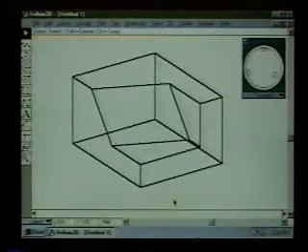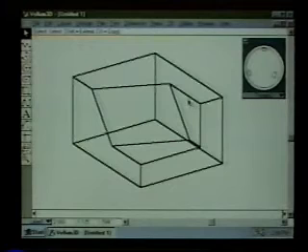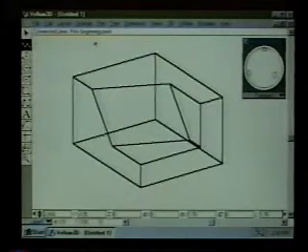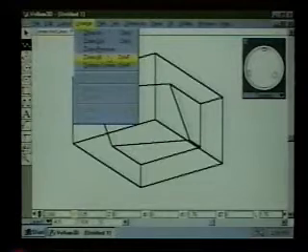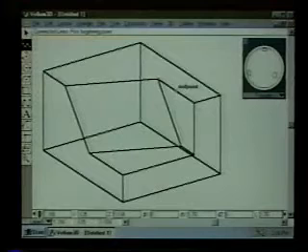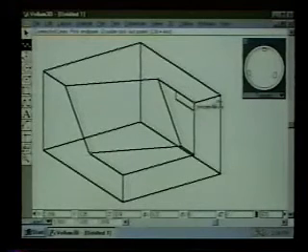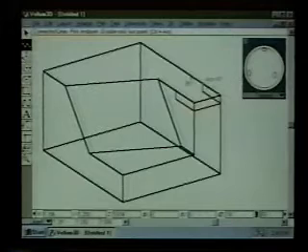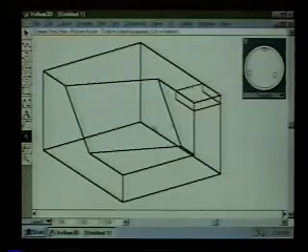Now I'm going to do some other operations. Let me put a notch in this end corner here. So I'll use the connected line tool. Let me say zoom all just to get this as large as I can. And then this notch, I just go and I find a midpoint, I drop down a little bit. And these alignments, again, happen automatically because of the drafting assistant. And then using those red lines to act as trim boundaries, I can trim off these lines here.